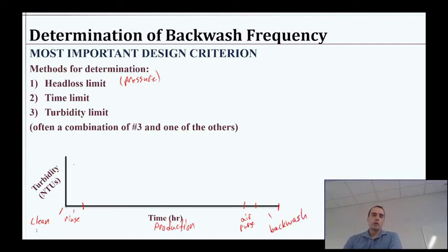So what does turbidity do then over the course of this period? And how does that relate to some limit we might place? Let's imagine we place a limit to say, well, if it's any dirtier than this amount of turbidity, then we're worried about safety and the effectiveness of our disinfection step next. So anything above that turbidity limit we're gonna say we should not operate. Okay, so that's gonna be our somewhat arbitrary, maybe there's some rules in place, turbidity limit.